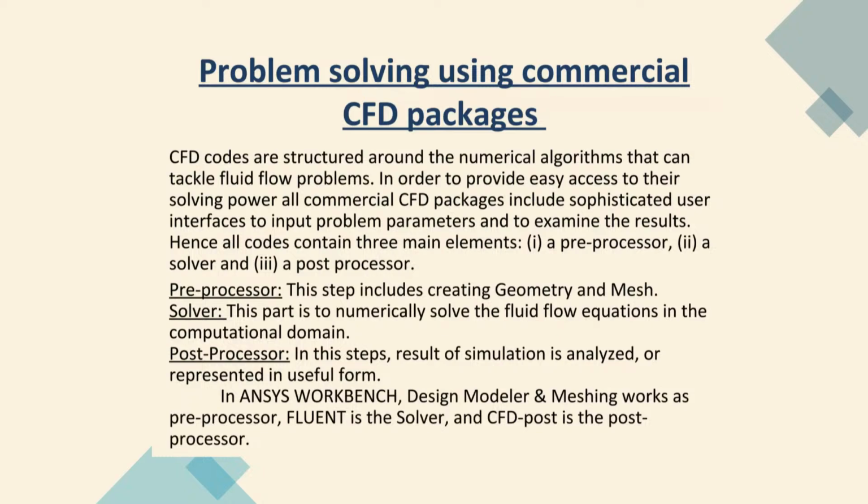Initially you think about which problem you are going to solve, you find out what the boundary condition will be, what the initial condition will be, what the geometry will be. This is called the preprocessor. Then you put everything in the solver, and it is solving. But after it is solving, what do you want to do? You need to present the results. It is solving and storing data at all the nodal points.